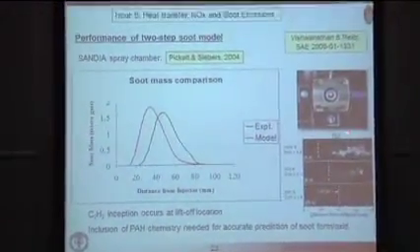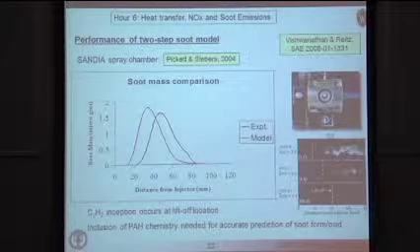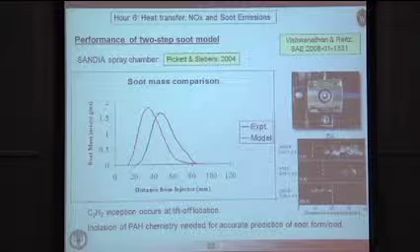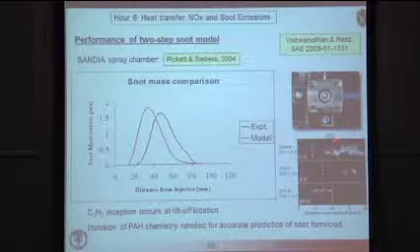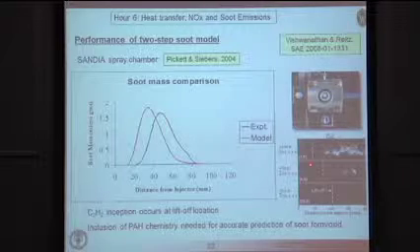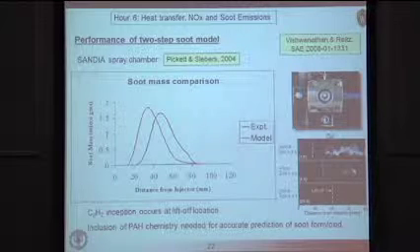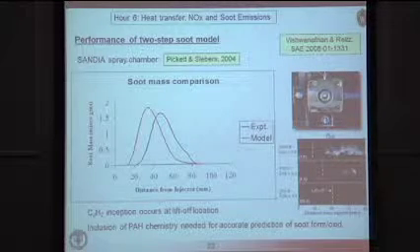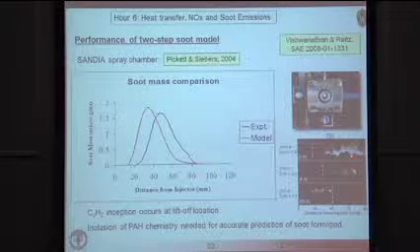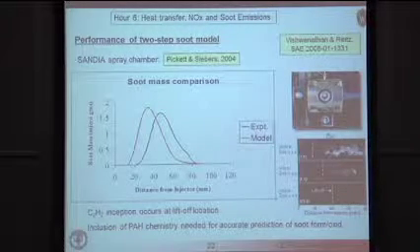The next step was to assess the performance of the soot models against experimental data. So we have some data from Lyle Pickett and Dennis Siebers at Sandia where they have this constant volume vessel. They measure liftoff length. I forget which fuel this was here, probably it was n-heptane. Liftoff length as a function of the temperature of the gas in the chamber, which essentially establishes the location of the flame. And then downstream of that, they use LII, laser-induced incandescence, to measure the amount of soot as a function of position, and also for these different images for different temperatures in the chamber.